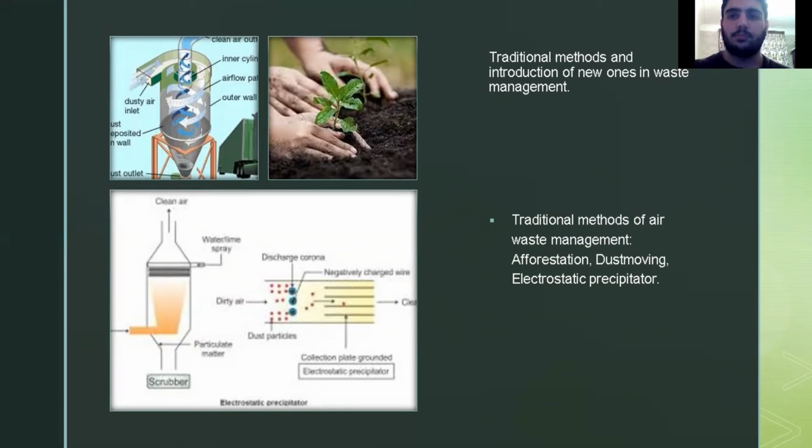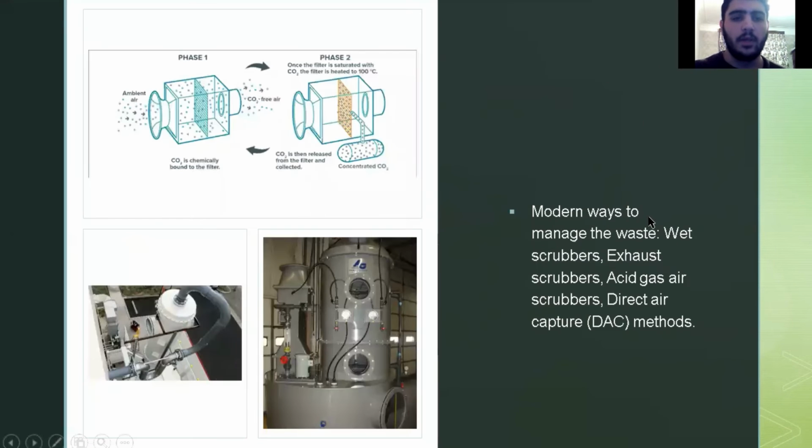So modern methods. Wet scrubbers method. Water-soluble gas and vapors, as well as particles and aerosols, are removed using wet scrubbers. Diffusion, which is restricted by vapor-liquid equilibrium, scrubs gas. Particulates are scrubbed by mechanical impaction and interception processes, which are dependent on the particle size and speed in comparison to target, such as a water droplet or wetted surface.